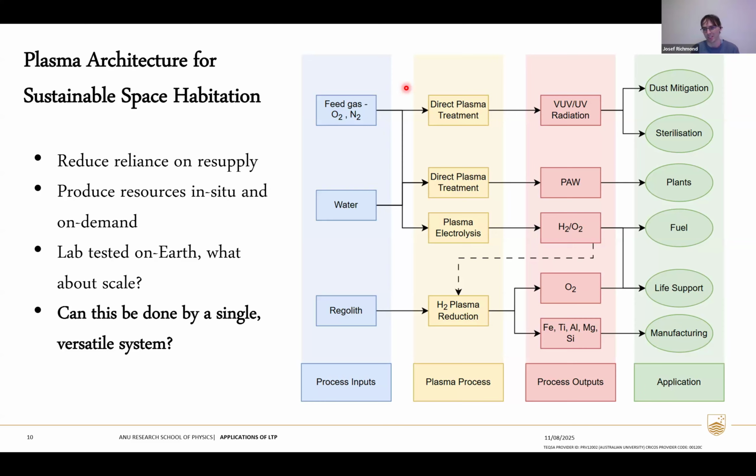It's an interesting test because it's something you wouldn't necessarily see with the standard UV tests, because they use much higher wavelengths and lower energy. For something like that beta cloth, I haven't seen much in terms of degradation or surface effects, but quite a few polymer surfaces really don't handle it well. So this is still something you could do, but you have to be very careful about how you apply it.